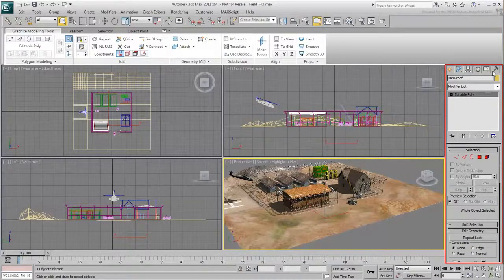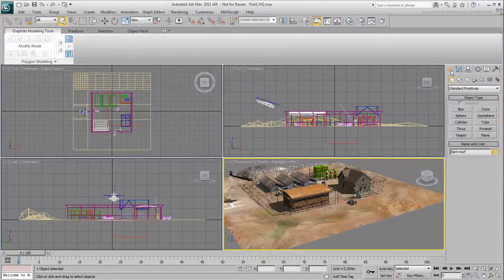As their name implies, the first is used to create geometry and the second to change parameters and modify the shape or aspects of objects. Let's take a quick look at the Create panel. By default, it's set to geometry, which are objects that have a volume. There are other types of objects, such as 2D splines, lights, cameras, animation helpers, and so on. At the geometry level, you can access additional types of 3D shapes from the drop-down menu.